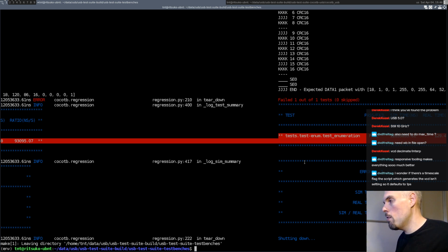So it needs to handle the retry procedure, because errors do happen. Sometimes it might be rare, but everybody tests that the core works when everything is fine and there are no transmission errors. Testing that it responds to errors properly and according to the specs is obviously not as tested, it seems.